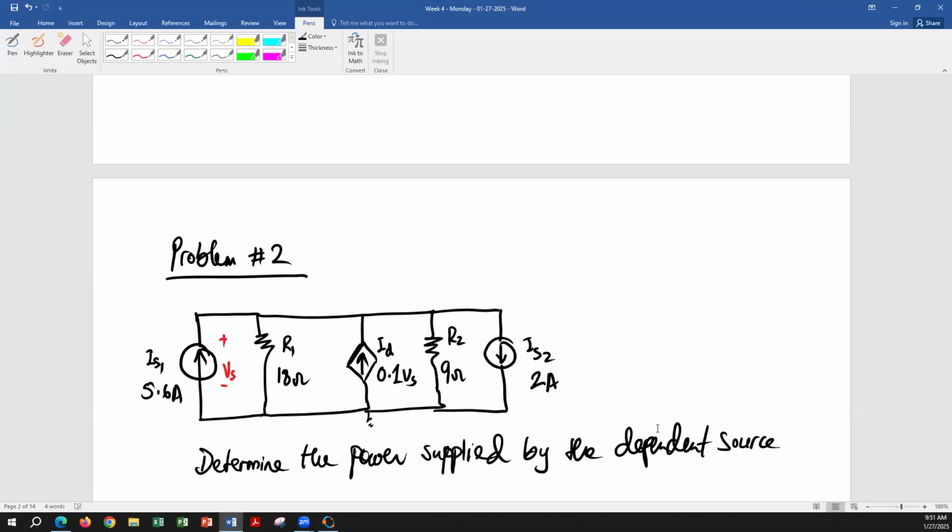How many meshes do we have? Anyone else? Yeah, one node. The voltage of that node is Vs. So why are you even going to the mesh analysis when you only have a single node on top, and that's the voltage that you're trying to find out. That's the voltage Vs, the node voltage on top.